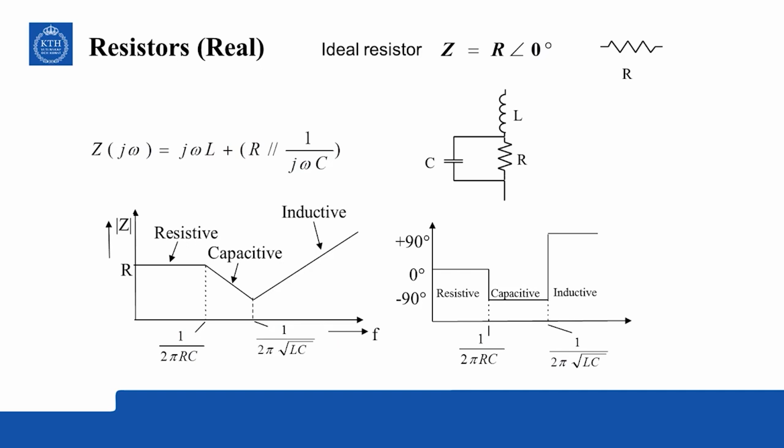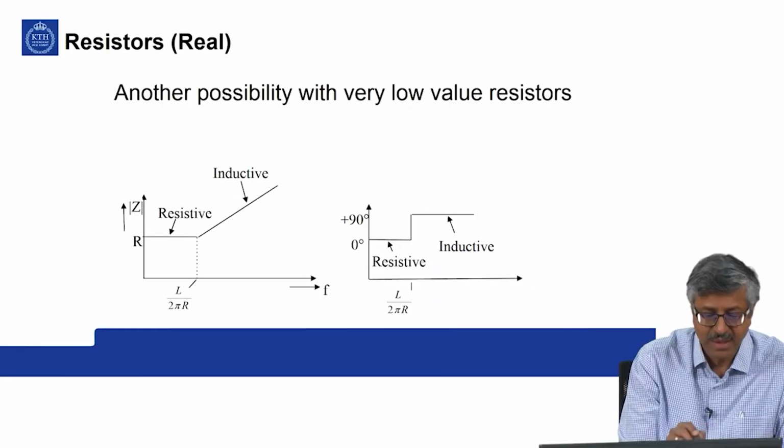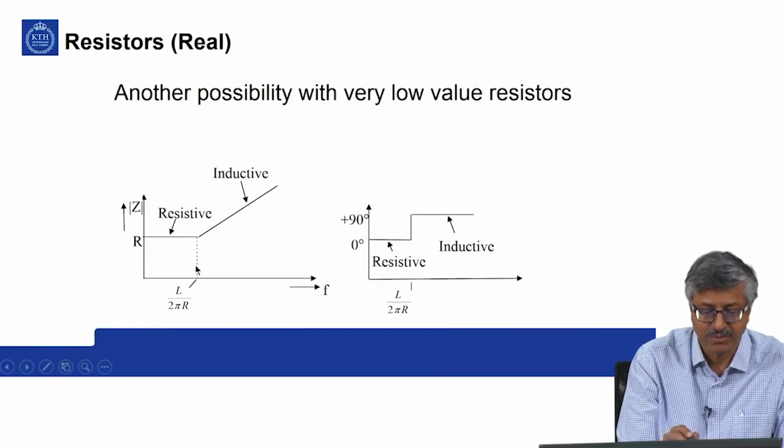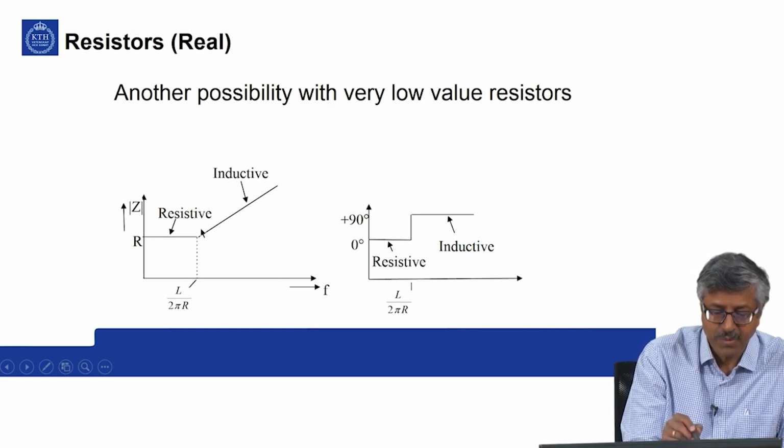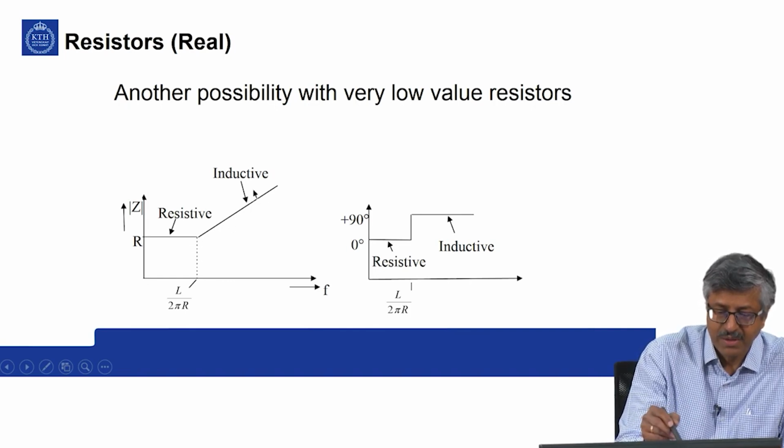At this frequency, when R equals 2 pi f L, beyond this frequency you have an inductive increase of 20 dB per decade.